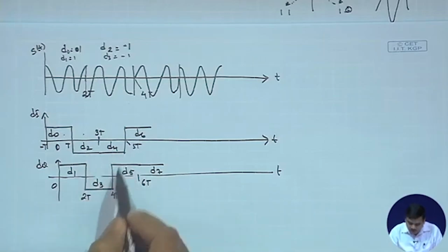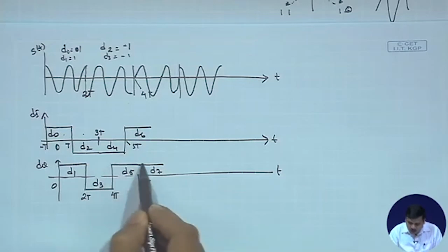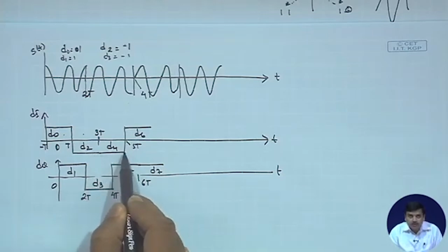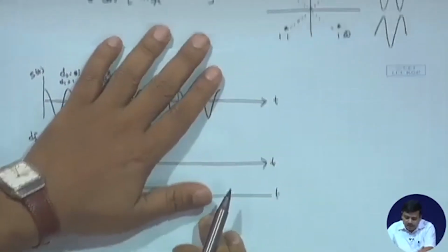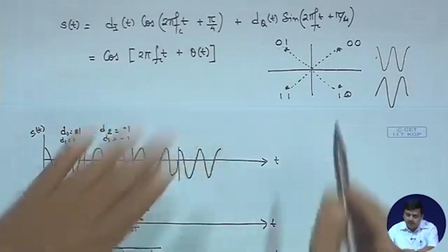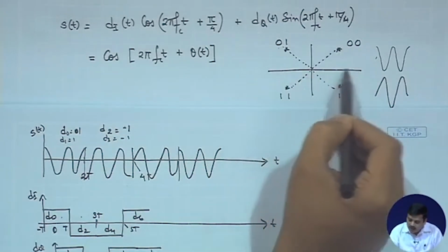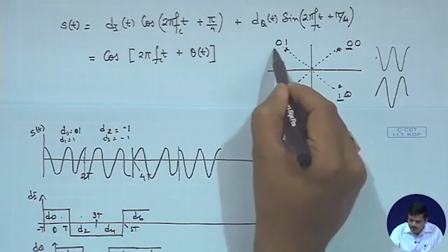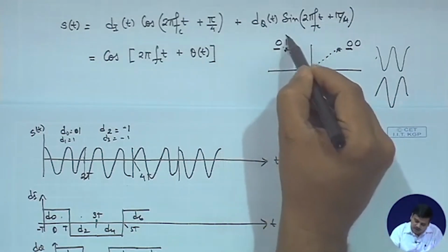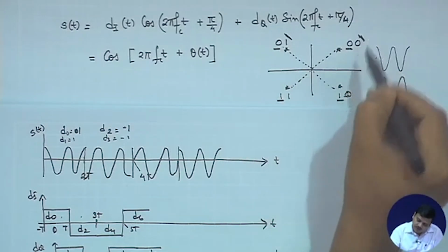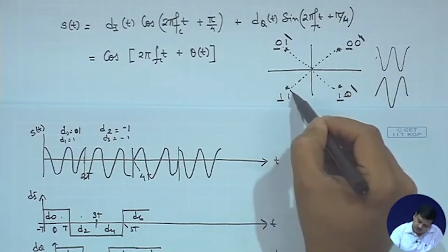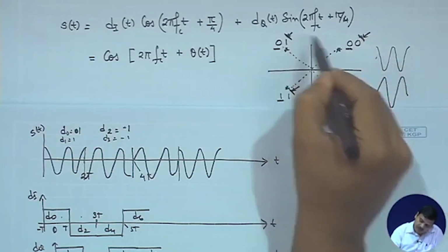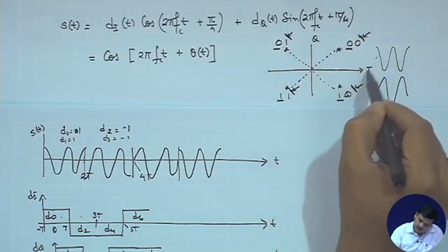What we find over here again is that the odd one, that is the Q channel, changes, whereas the even continues. So, what this means is that in this diagram you are changing either the I bit or the Q bit. You could identify this as the I bit, and the second bit as the bit for the Q axis, and this for the I axis.